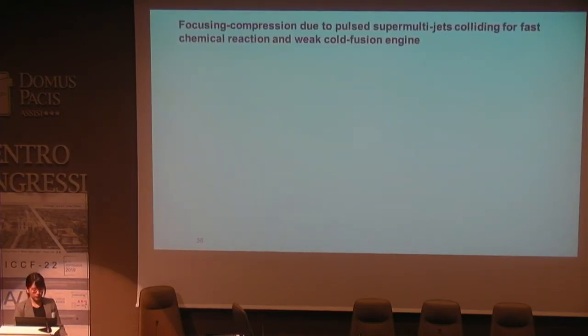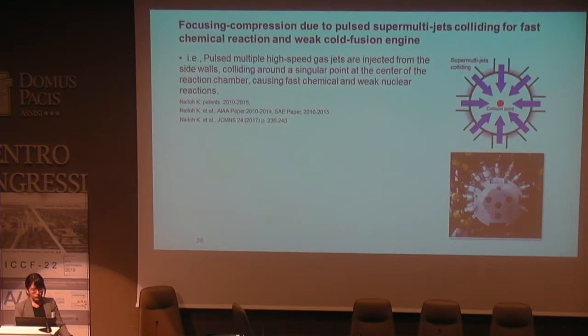So this will be a repetition of what I said before, but we have previously proposed a new principle for generating reactions, which is called focusing compression due to pulsed super multijets colliding for fast chemical reaction in weak cold fusion engine. In this principle, multiple high-speed gas jets are injected from the sidewalls, colliding at a singular point at the center of the reaction chamber, causing fast chemical and weak nuclear reactions.